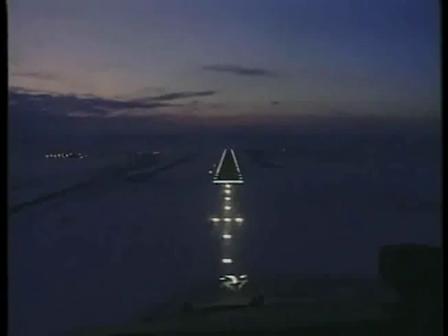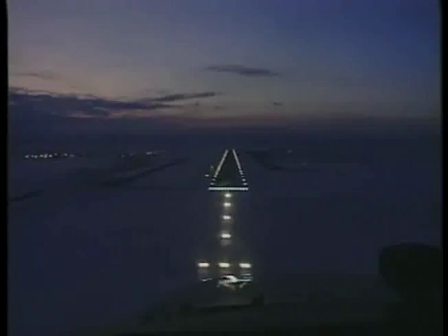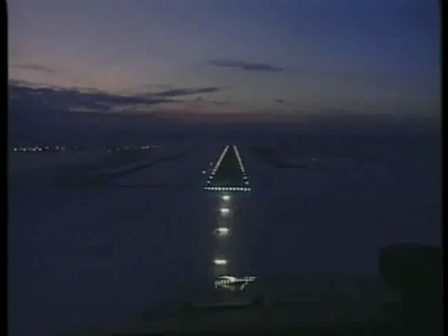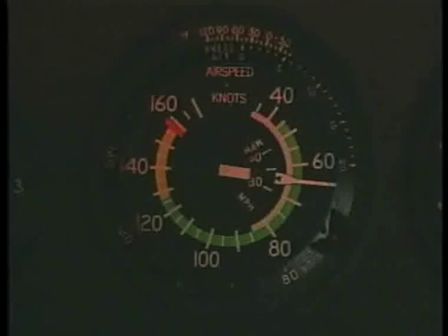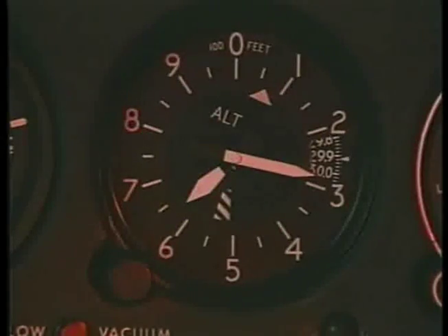If glide slope information, such as a VASI or PAPI, is available, it will help you maintain the proper descent attitude. By carefully monitoring your flight instruments and power setting, you can help to ensure a smooth approach and landing. You should practice night landings both with and without the landing light to enable you to make a safe landing in case the light fails.